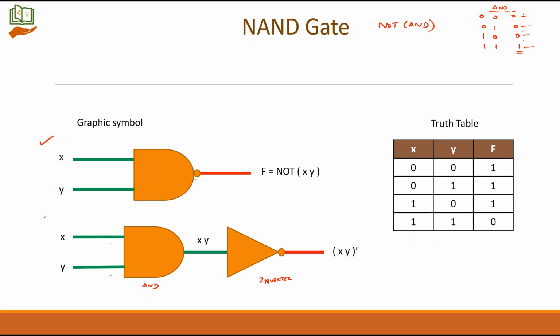This is the overall symbol that you should use. As I said earlier, this is actually the detailed circuit. This particular symbol is actually the inverter symbol. This is the AND gate symbol. That is what is elaborately represented here through this diagram. There is nothing wrong when you use this diagram, but when there is a specific gate for NAND, you have to go with this. Though the output is going to be the same, this is just used for explanation purpose alone. So what is NAND gate?